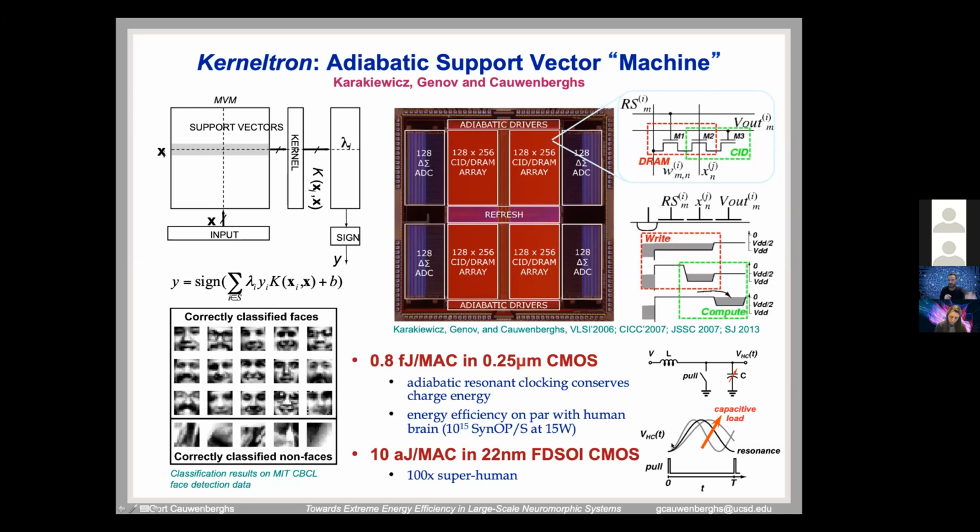with a CMOS inverter, where, as I mentioned, if you drive a line between 0 and VDD, up and down, every time you go up and down you consume energy. The total charge is C times VDD. That's the charge you need to deliver as you charge the line, and it is delivered from VDD and returns back to ground.